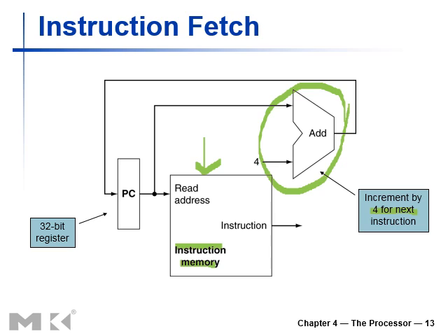If you remember that the instruction memory is the byte oriented memory, and our machine code, in order to store a word, we have to have the 32 bits data in order to store in the instruction memory. We have to utilize 4 dedicated locations in order to store a machine code of one instruction. So the next instruction machine code will definitely be the 4 incremental away from the base address. So we have to add the 4 in the current address in order to generate the next address of the instruction in a normal flow of execution, which later on we will see how we're going to change that. So these are the major components that are used for the instruction fetch.